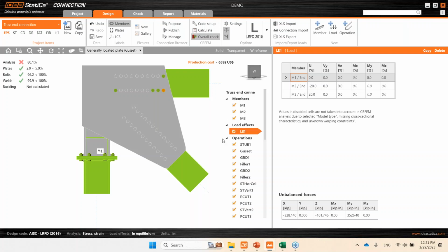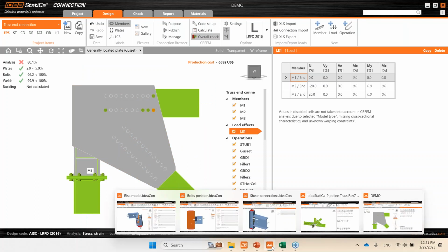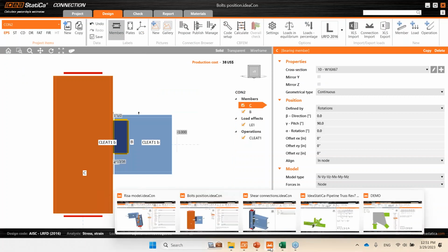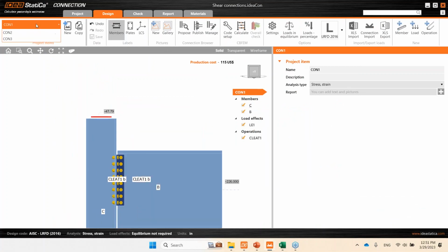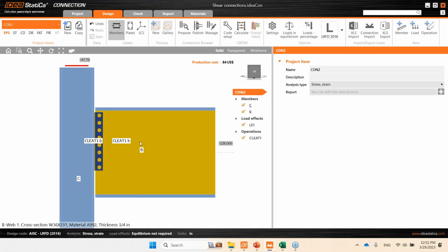Could we assume that a shear considered at the node is more conservative than an additional moment that is induced in the offset connection? That could be more conservative. It really would depend on the actual model, I guess, but depending on the forces and how the different forces interact with each other, there is a chance that shear could be more conservative than some moments. Yeah, I believe so.